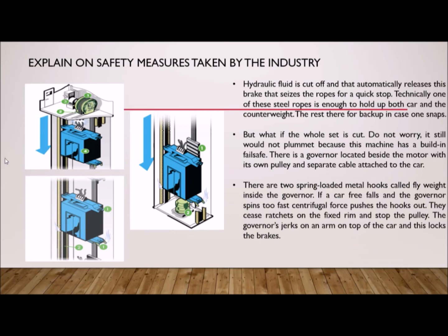Okay, but what if the whole set is cut? And this picture too. Do not worry, it still will not crash because this machine has a built-in failsafe. There is a governor located beside the motor with its own pulley and a separate cable attached to the car. There are two spring-loaded metal hooks called flyweights inside the governor.